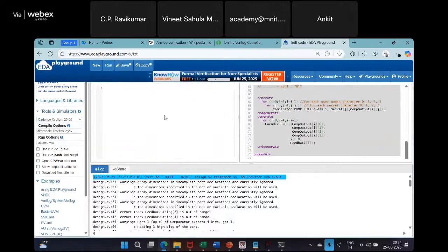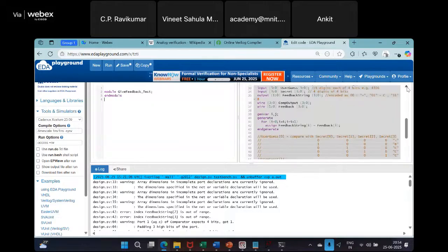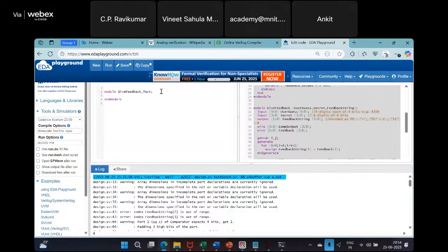and we'll write a test bench. Okay. So module give feedback test, right? And we'll have to instantiate one copy of feedback. For that, we'll need user guess, reg [3:0] user guess, then reg secret, then the feedback string will be [1:0],